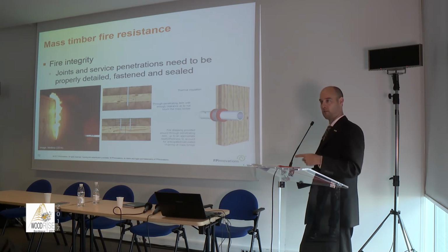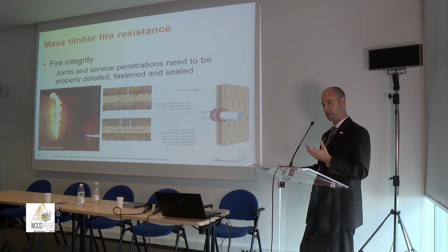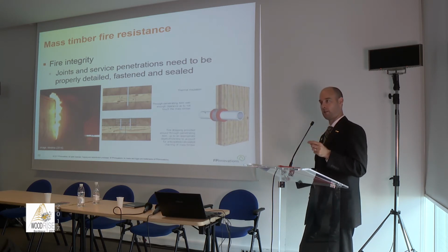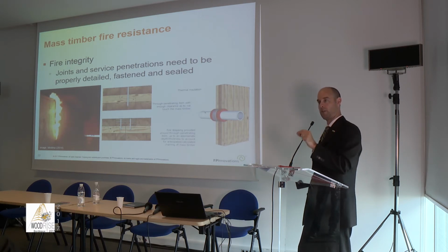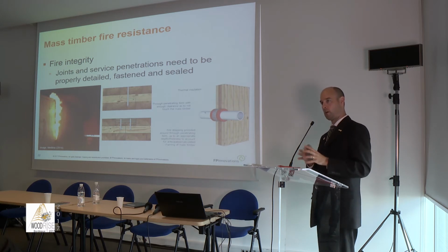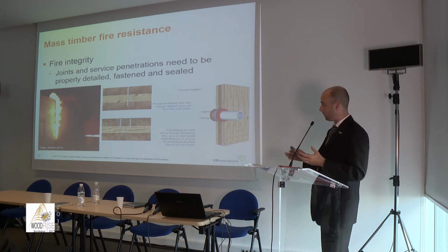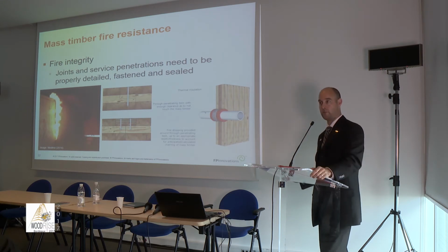So you have to put some insulation around it, and then you put the seal on top. So in the event of a fire, if that pipe heats, it will not accelerate or induce charring on the side of the element. So you have to protect all of these and think a little bit differently. But overall, all devices that we tested for concrete really work well.